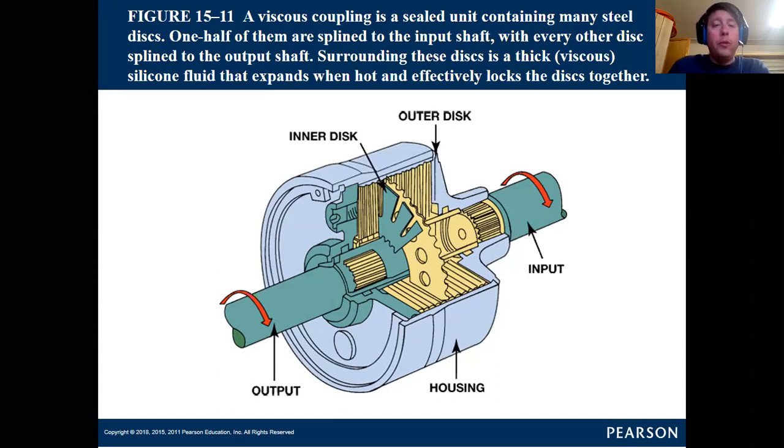You literally are in four-wheel drive like a normal pickup truck, and you can drive it on the interstate 80 miles an hour around curves and never have any type of bind-up issue. A lot of the componentry looks identical to a normal pickup that's just part-time. But the transfer case itself is designed in such a way that it can split the power between the front drive shaft and the rear.